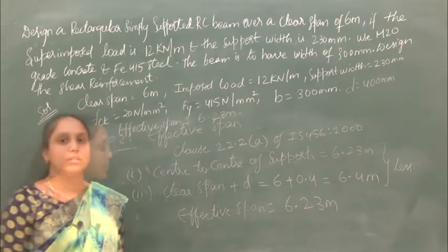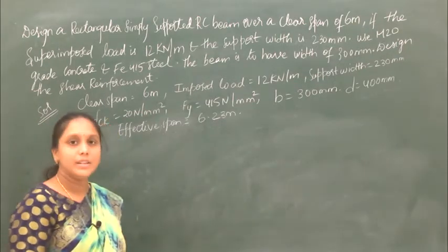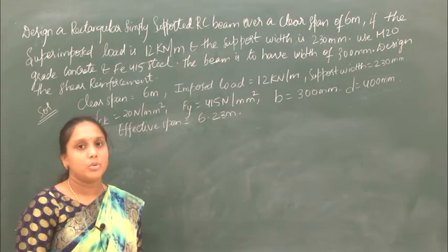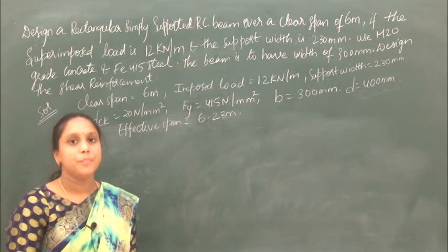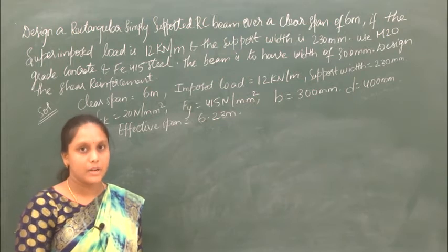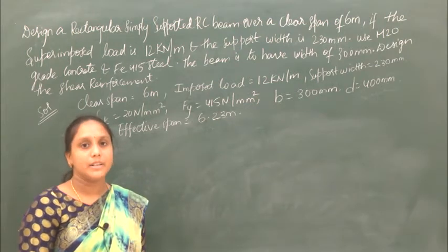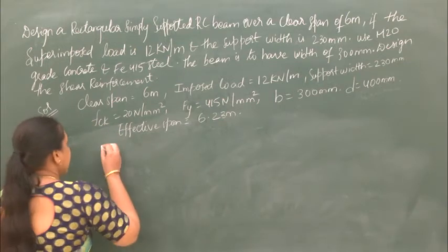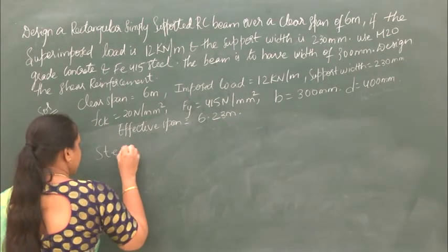Now we have calculated the effective span. So the next step, we have to calculate the factored bending moment and the factored shear force.